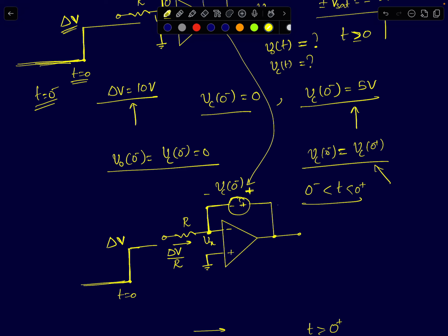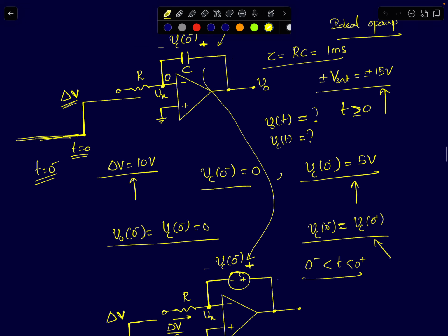If there is an impulse current in the circuit, yes, it can change instantaneously. But in this circuit there is no scope for any impulses. You are applying a step input to the resistor, so there can be a large value of current, but still, for the voltage across the cap to change instantaneously, you need to supply a sudden impulse of current.